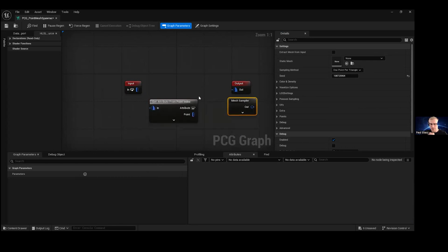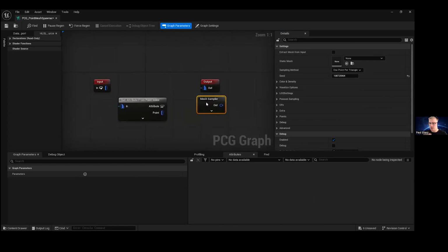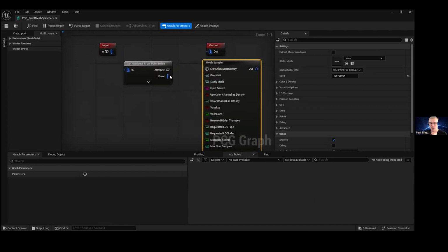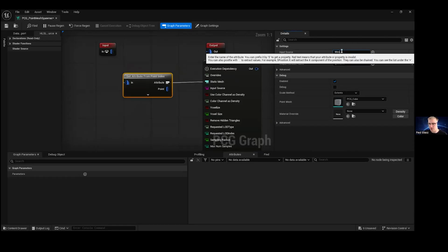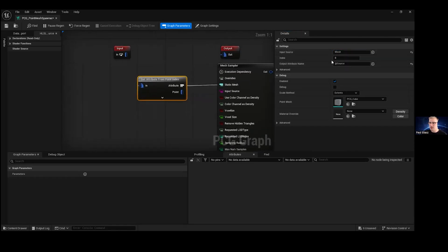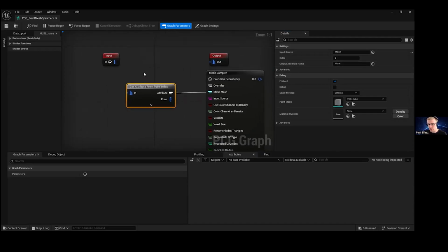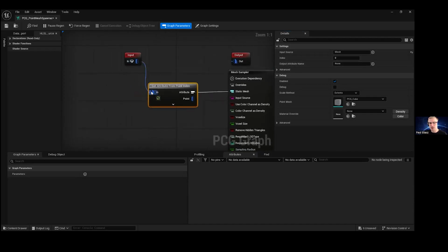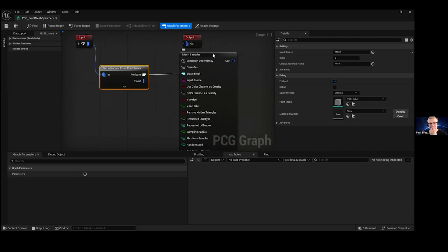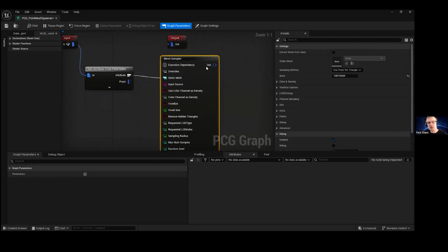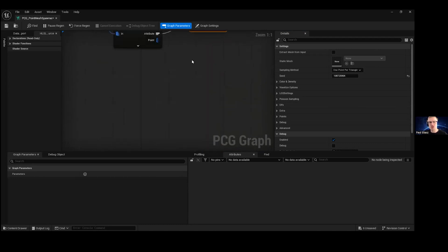For this one, because we're going to use static mesh, which is already here, this is going to be our attributes, right? I also want to make sure that all the information we're working with is input source as a mesh, because we're going to use mesh for this specific example. Since we are dealing with mesh, make sure output attribute is set to none because we're not going to deal with this. Our source is going to be this one. So I'm going to connect this to this. Our attribute set point from get attribute from point index is connected to static mesh.